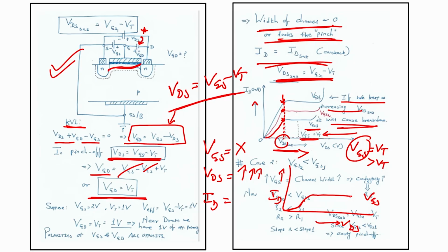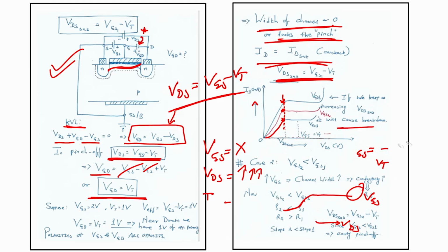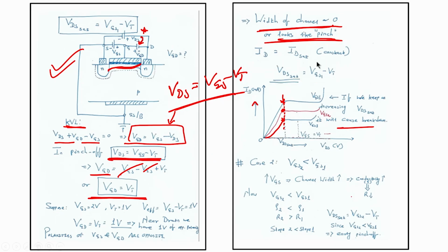then suddenly you will see that it starts to break down. Suddenly the current shoots up, and this is my breakdown condition. Alright, and my MOSFET can be damaged. So, what we understood is that for a constant VGS we can apply VDS, but if we exceed a certain voltage of VDS we may see the breakdown effect, okay.